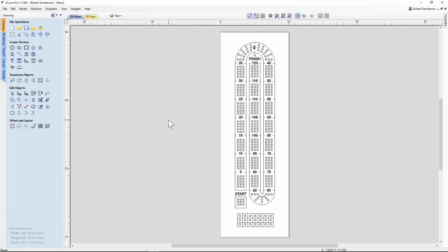So one might think, well, we've got the cribbage board resized, we're ready to go to the toolpath and start cutting. But the reality is, when we enlarge this, we change the size of not only the text but all of the holes. So now the 3/16 inch pegs will not fit into the holes properly. So first we must ungroup what we grouped. You can tell it's ungrouped because it is now all shifted to the dotted lines.